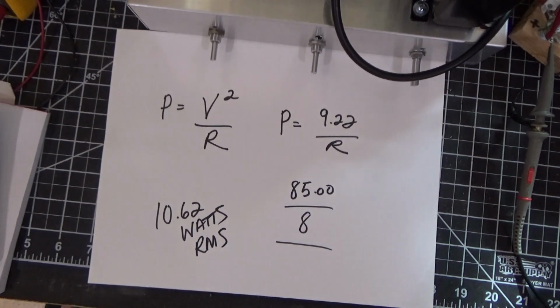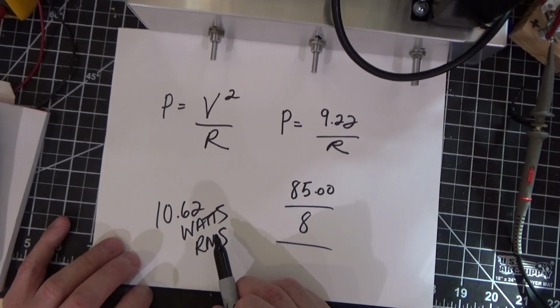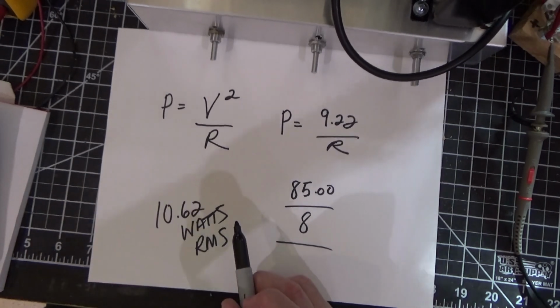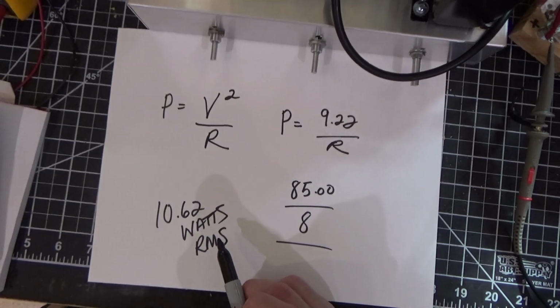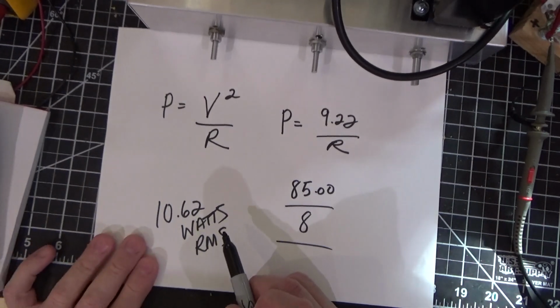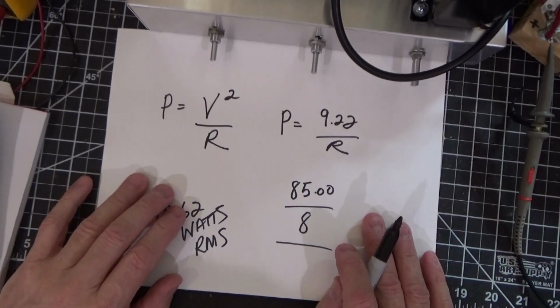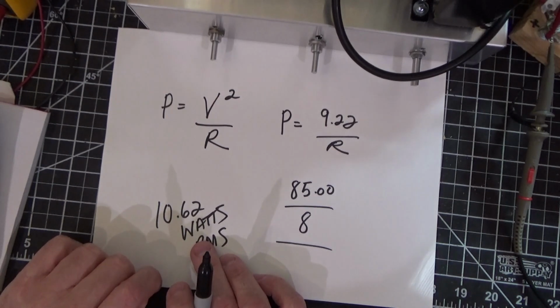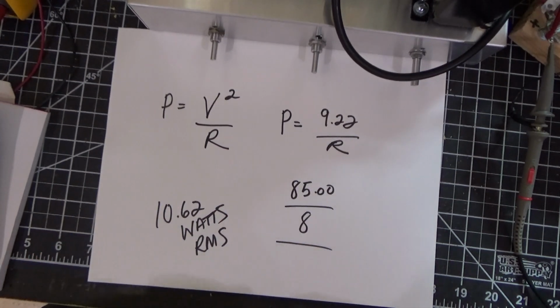Very respectable for this amp. Okay? Now keep in mind, it is a 15 watt amp, but this is right before the signal starts to break up, right? We never want to just continuously overdrive an amp. So what this tells you is that we're getting 10 watts out of the amp before it starts to break up. Now we could adjust the cathode bias resistor and maybe tweak this up a little bit. We could absolutely do that. I'm not going to do it in this amp because I'm satisfied with it the way it is.